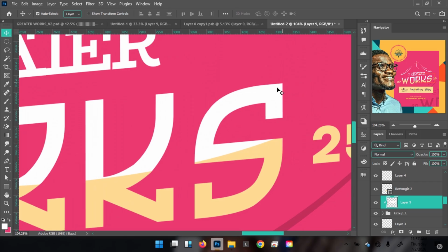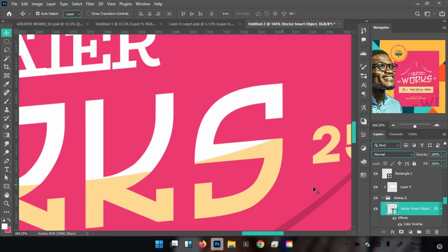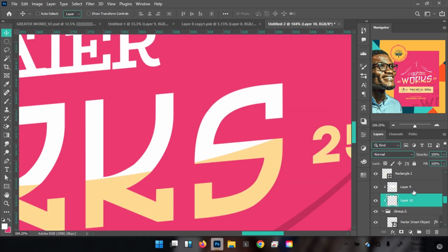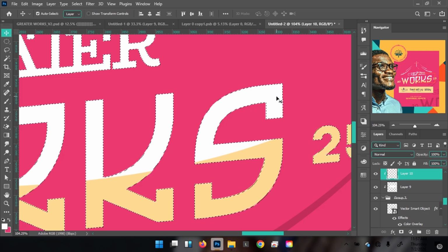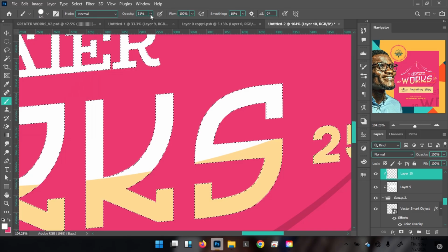In here, I added some slides, some small things to the edges to also add up to the effect. So I created a new layer, enter, and then I cleared the mask. Now moved it up. Held Alt, click here, Control click inside the thumbnail to get the selection. And B for the brush to select the hard round brush, 100% opacity, and then reduce the size like so, and apply on the edges.